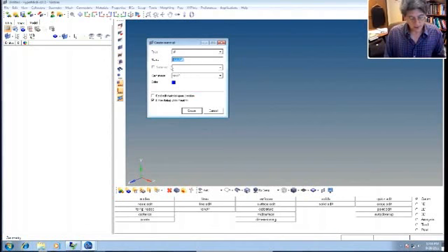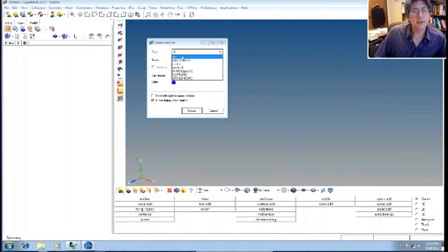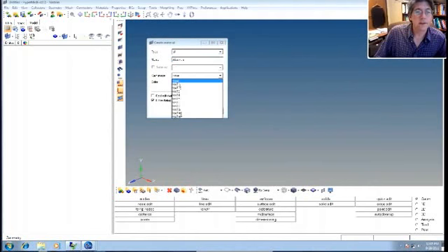Here you can give the material a name. We'll make it out of aluminum. And then if you do create, don't worry about "all" so much. It just allows you to sub-select different types of materials. So if you pick isotropic, you can see Mat 1 goes away because Mat 1 is an isotropic material. If I pick all, Mat 1's available again. There it is. All right, so let's create.